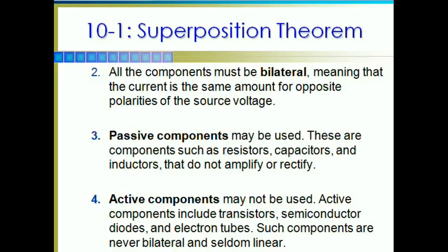Now you can use some passive components. Resistors, that's pretty much what we've been talking about the whole time up to now. So resistors, capacitors, inductors, they don't amplify for the most part, especially with capacitors. It doesn't matter what direction you put them in. Of course, there are capacitors that have direction, they have polarity, but not all. You can use those kind of items. They don't amplify or rectify anything in any way.